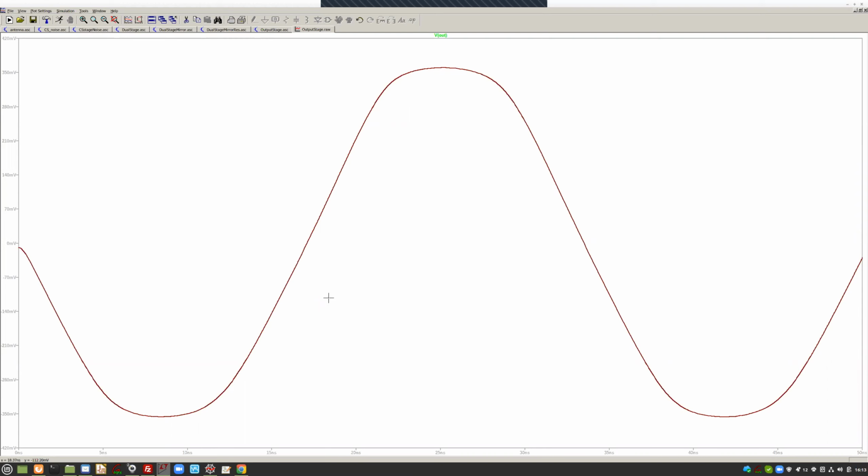And of course you can do higher currents, making the width larger, but there's no showstopper here in the process, so that we cannot drive it from within the power supply. I just do 250 millivolts peak at the input, which is not outside the range of the power supply. So it's 500 millivolts peak to peak, and I obtain the correct output value.